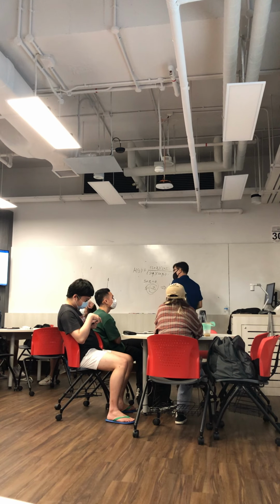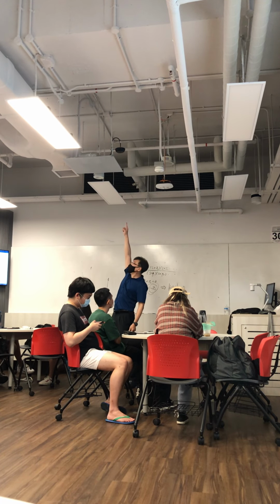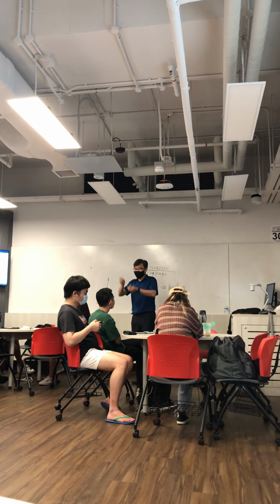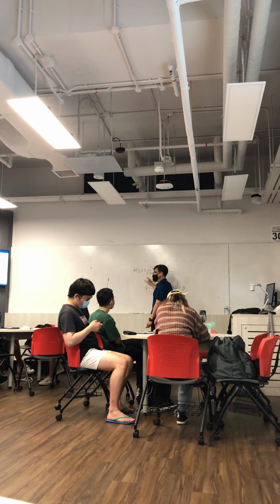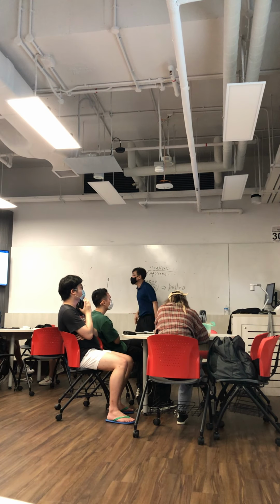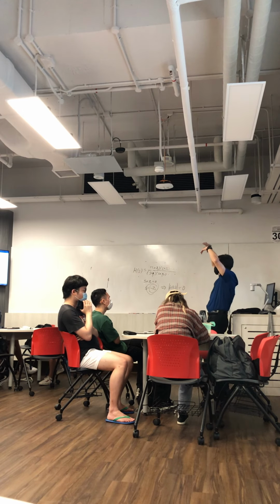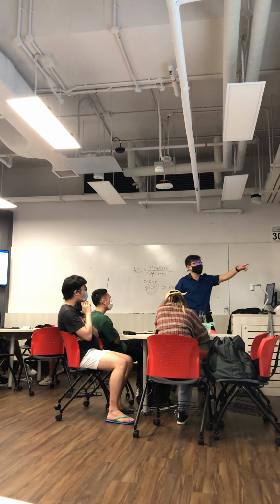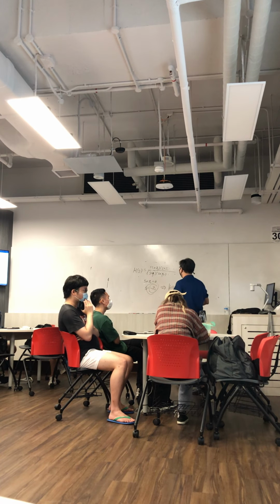Another thing: what is a pole? It's not so complicated to understand a pole. It's really like a literal pole, when you see a pole very tall, right? So why is it called a pole? Because imagine if any of these factors in the denominator goes to 0, this guy goes to infinity. Infinitely high, it's like a pole. But in a real world system, you can never go all the way to infinity, so it will chop off somewhere at saturation. So you can see at which frequency point you have the pole, and it comes from all this.